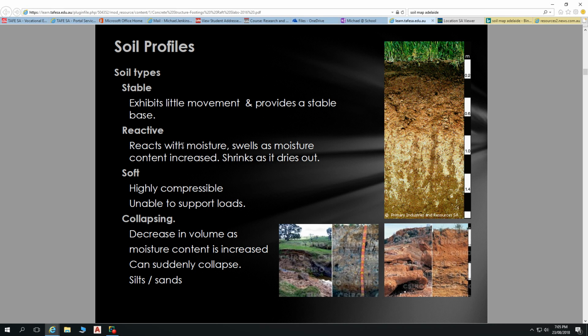But one of the things you had happening in Christchurch with the earthquake was a similar sort of thing, but no water involved. You had shaking of the earth and sand particles sitting together better, and that removed support for buildings as well. So you not only had the earthquake loads going on, but you had soils collapsing as a result of that vibration and settling.